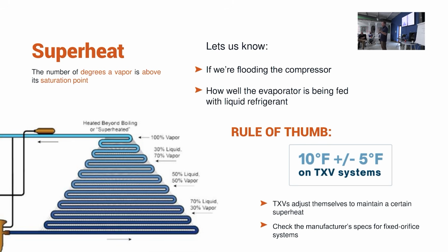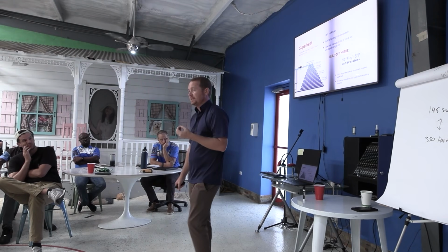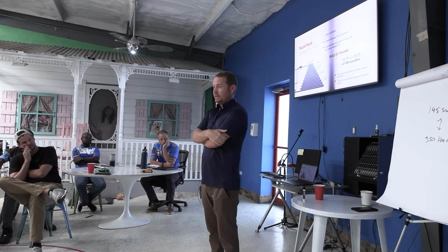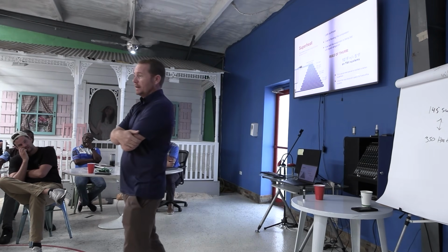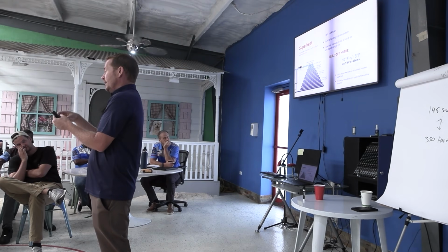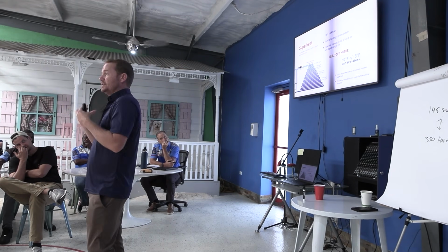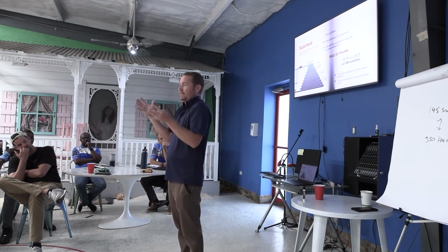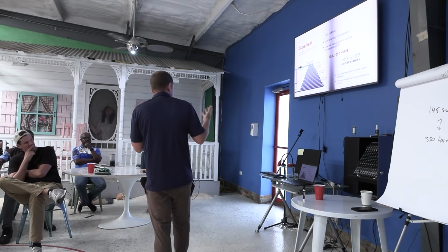That is your typical operating range. Now, you're very rarely going to see 5 degrees of superheat. That would be very abnormal in the world that we work in, especially outside where we measure it. You will see it sometimes at the inside. But there are actually a lot of manufacturers, and we see this a lot with Carrier, where the valve is actually setting superheats that are too low, and they will actually go down to 0 superheat. And in a lot of cases, it's just because of how the bulb is positioned, how the bulb is insulated from the factory. So in a lot of cases, I've had to go in and actually insulate a factory bulb in order to get that superheat where it needs to be, right? It's because the ambient air is affecting it and driving the valve too far open. So that is something to pay attention to.